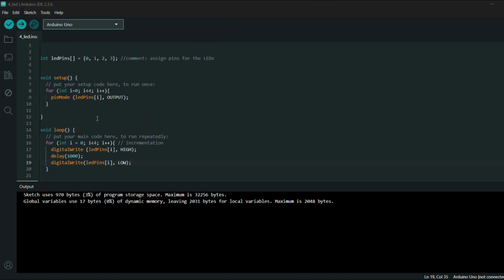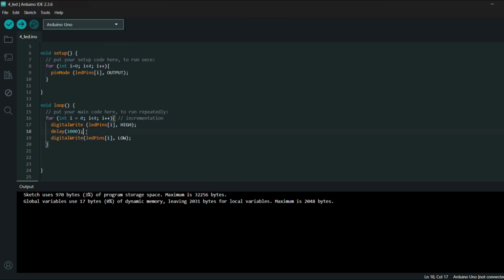And in our microcontroller IDE, we now see this delay. This delay is responsible for the time delay between the transition of the LED on and LED off. So this delay in between specifies the transition between the on and the off. So if we now increase it to 2, that means 2000 milliseconds. So it is equivalent to 2 seconds.